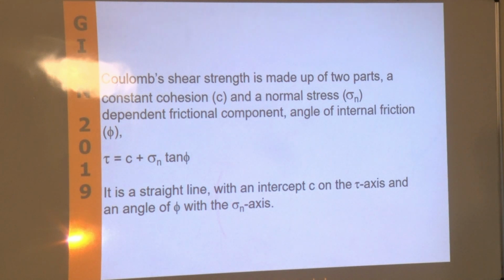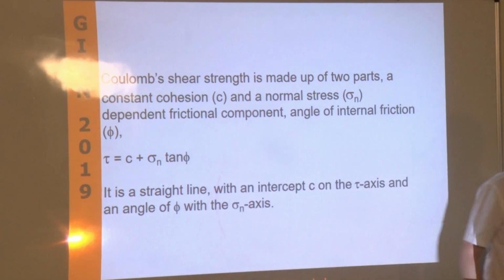Formulation? Well, basically that's the equation. This is one equation that you should remember. I think you did that in high school, I believe, in physics, maybe even in middle school. And the end is that shear is equal to the cohesion plus the normal stress times the tangent of the friction angle, or the friction coefficient. Okay? Tangent of the friction angle is the friction coefficient. That's pretty much what it is. And it assumes that the failure happens along a straight line.